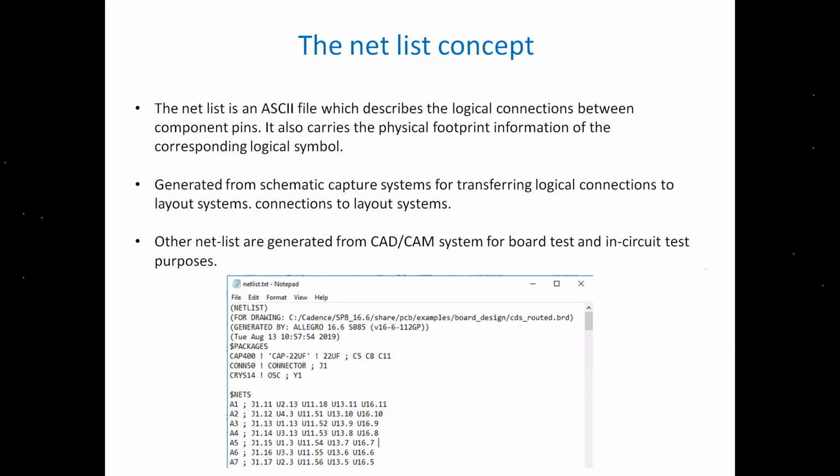And the netlist concept comes here in the schematic side. In between, you are making the wire connections, right? That wire connection is called the connectivity information. So the tool understands the connection information as a net. See here below in the notepad, you can see the net information.